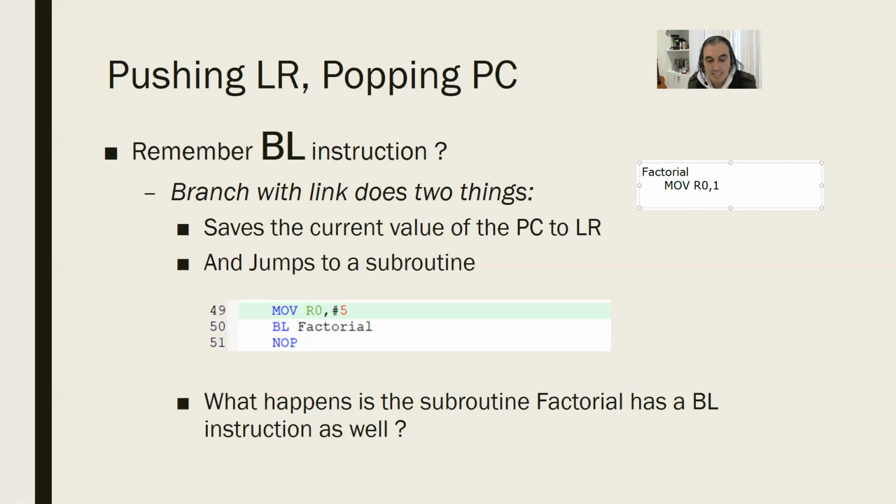And at that code, I have another jump to a subroutine, BL power. I have another subroutine, and I just have my code. And at the end, I say BX LR. This is how I return to here, right? And at some part of the instruction memory, I also have power.